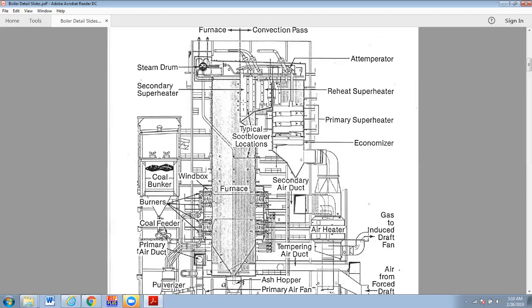So you've got to be careful in purchasing the coal and knowing the temperature characteristics of your boiler to make sure you purchase appropriate coal, or you can slag the heck out of a boiler in a very short period of time, because there's a lot of ash passing through the system.